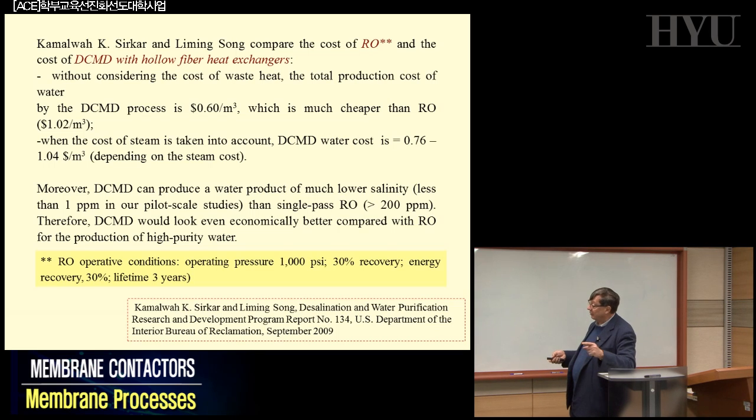That's why the real solution will not be trying to cancel reverse osmosis, but try to integrate reverse osmosis and membrane distillation. You can use the benefits of reverse osmosis in terms of much lower energy consumption than thermal system, up to a recovery factor of 50%. At this stage, when you cannot operate anymore reverse osmosis, you can introduce membrane distillation on the retentate or the concentrate of RO using MD, where MD can still work nicely with no problem at all.